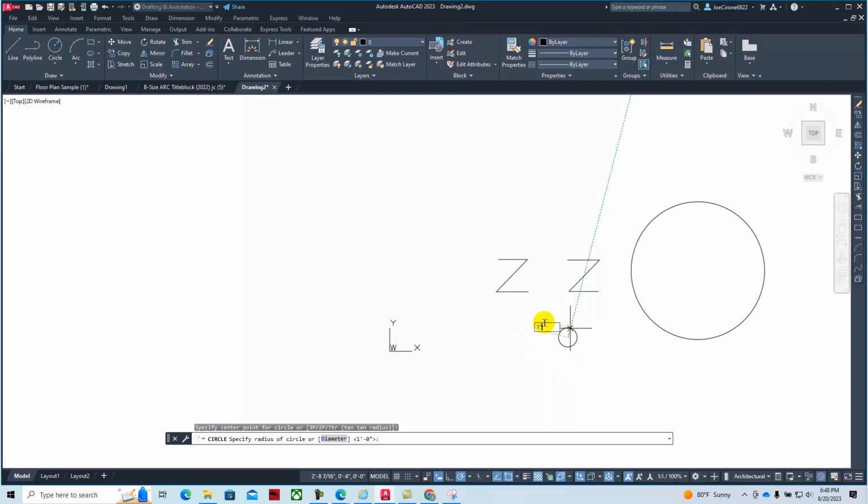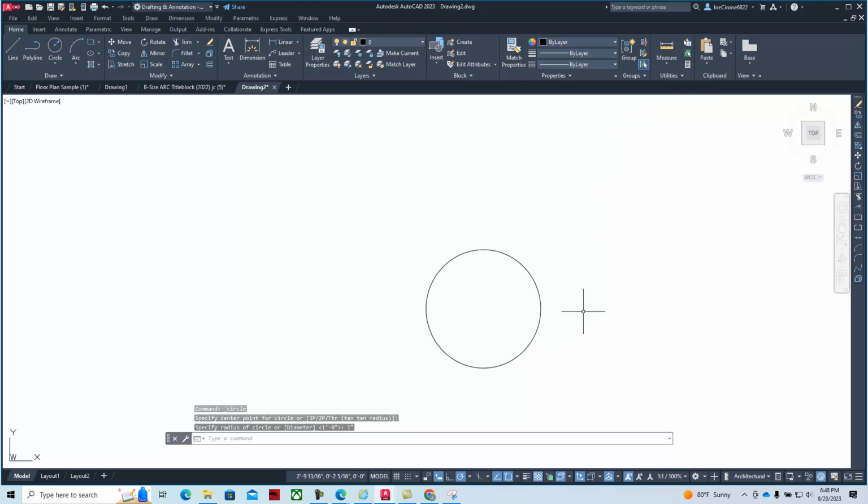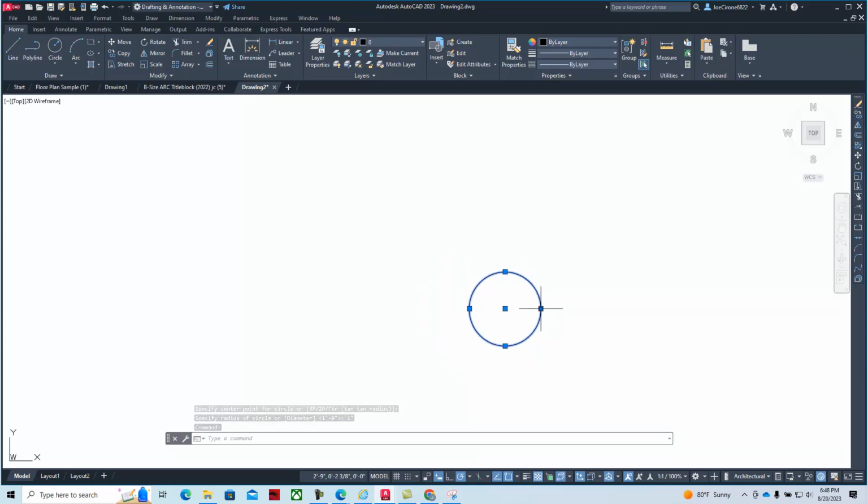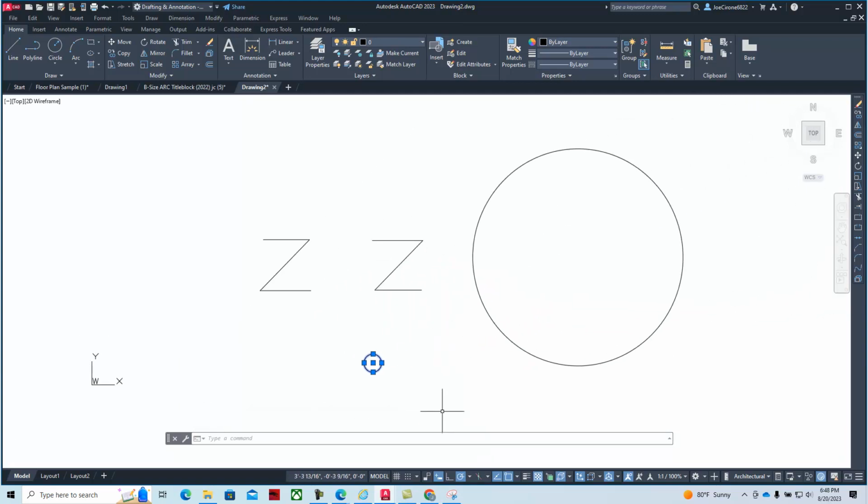And so when we input coordinates in inches, we'll use that format. So that's a 1-inch radius, and if I turn the wheel on the mouse and click on that, and then I hover over a grip, it'll show me that that's 1 inch. And so as we create these different geometries, I can hit escape to get off of that part.